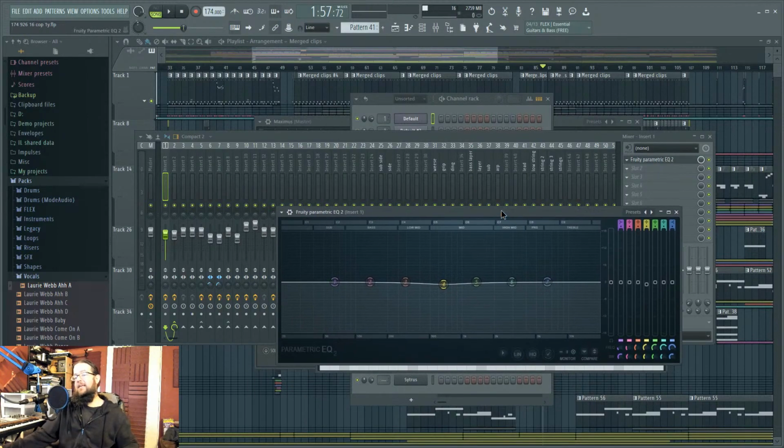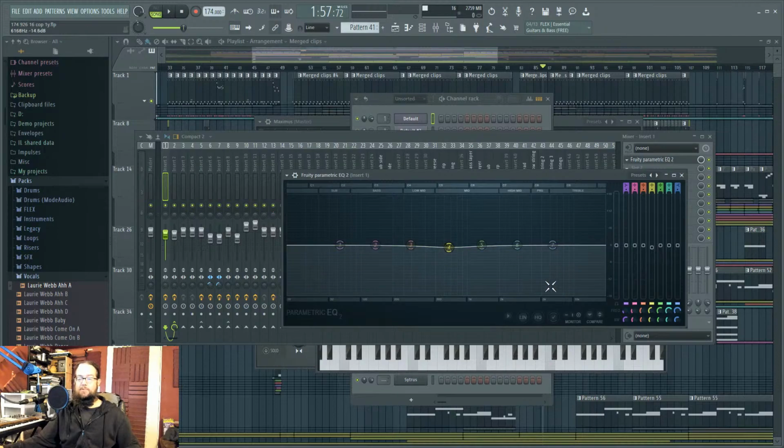This is something fun about EQ. Because this is something called minimum phase EQ. You might have heard of linear phase EQ. It's the opposite of what that is. Linear phase does not screw with the phase of your content when you make an EQ change, but regular EQs do. And it's because that's how filters do the work. They create phase change to stuff.